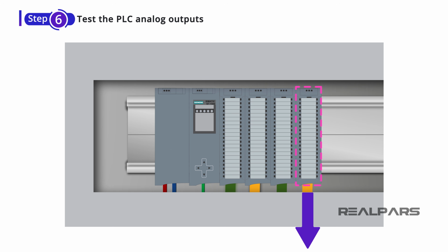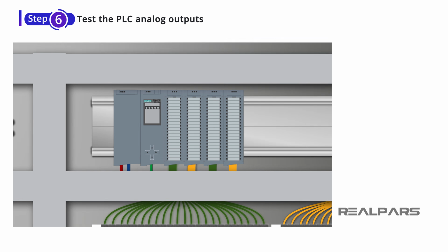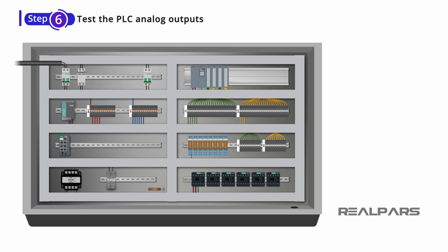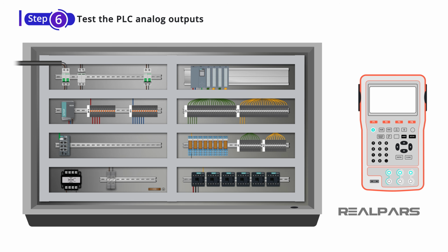An analog output signal could be either voltage or current. We can measure this using a simple digital multimeter as well. Most of the signal simulators can also be used to perform measurement functions similar to a digital multimeter.